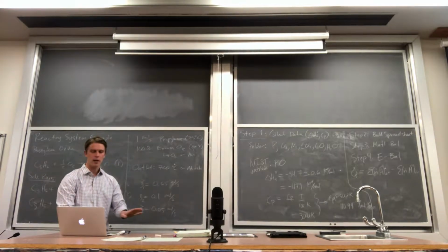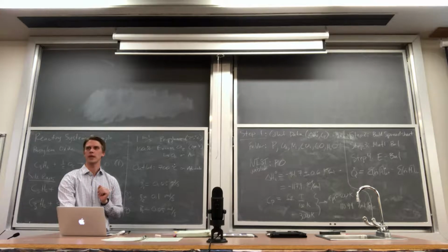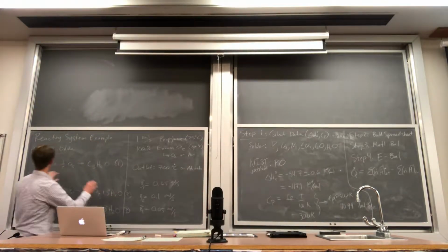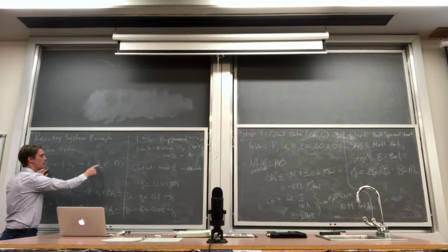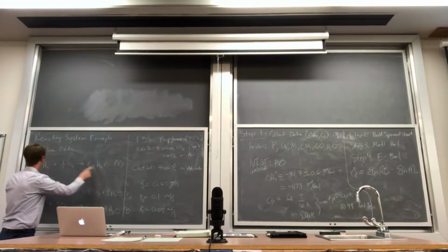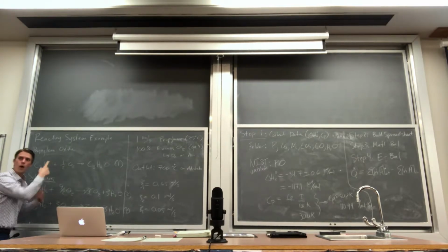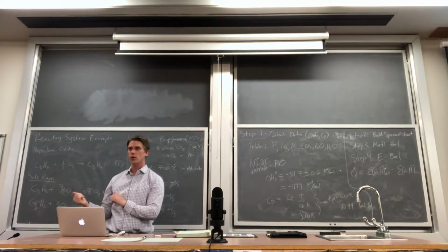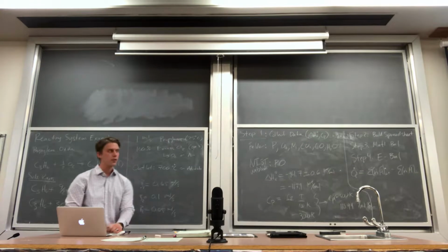In this particular problem, we don't really need to worry about the mole fraction. But if we did, if we had an equilibrium constant here, the equilibrium constant for this reaction, for an ideal gas phase reaction, would be the mole fraction of the propylene oxide divided by the mole fraction of the propylene times the mole fraction of oxygen to the 1/2 power. So if we wanted to calculate an equilibrium constant, we could. Or if we needed it to determine our extents, we could. So that's why I built a spreadsheet this way. Okay, now I have another column here for the temperature in.